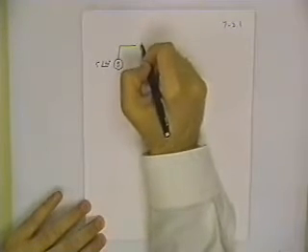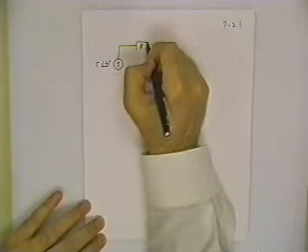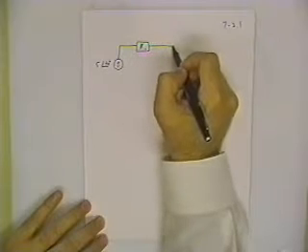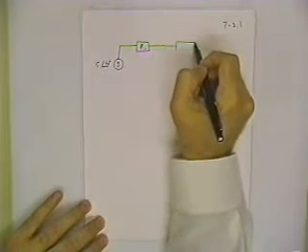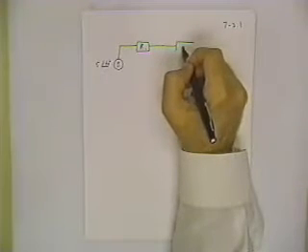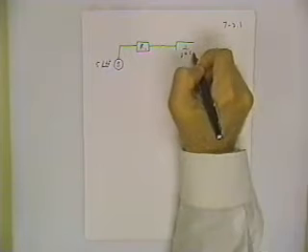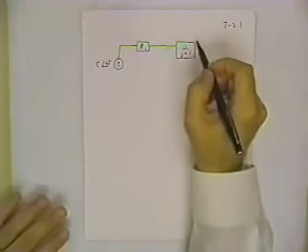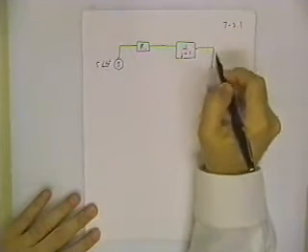Okay, and you have R1 as a numerical value of the resistance. That becomes the impedance for that resistor R1. For C1, we're going to put in the pure imaginary number 1 over J omega C1. And so on around the circuit.